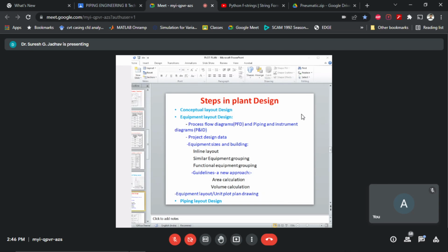The layout and piping arrangement characteristics of these shall be dealt with subsequently. However, certain general principles are followed in locating the same. The equipment is grouped to have the optimum location for minimum pipe run, and process flow sequence is followed to establish the functional performance.